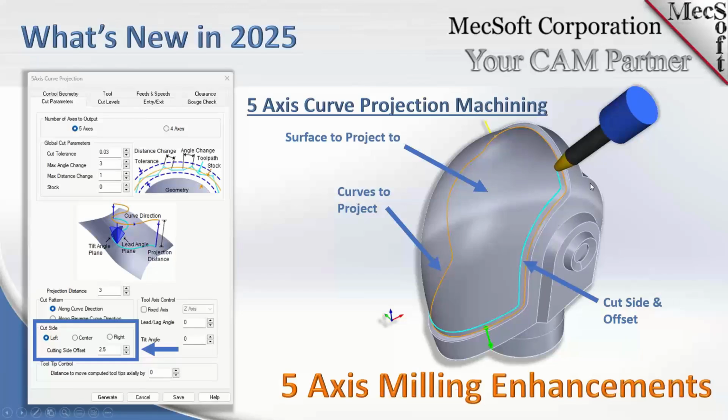So now what it does is it calculates the curve that you want to project and allows you to set an offset. So if we know the tool diameter on the tip of the tool is a certain diameter, you can offset that, say half of the tool diameter. Here I'm setting it to 2.5. And what it does is it calculates the offset curve and then it projects it down onto the toolpath. So you don't have to draw.